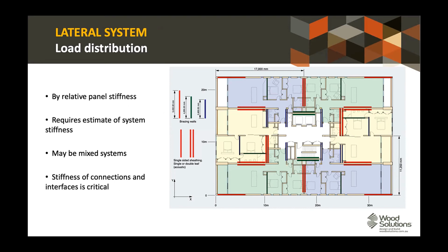And we're looking through this building plan where we know we have double leaves of walls, where we can then get two leaves of sheathing. And that's what this plan does: 3/6, 4/2, and 5/4 lengths distributed around the building. Now, this is not a uniform stability system. It's pretty much symmetrical, but it's not uniform.